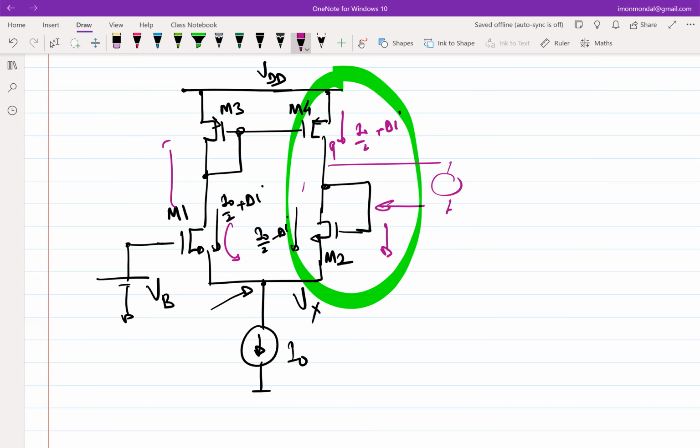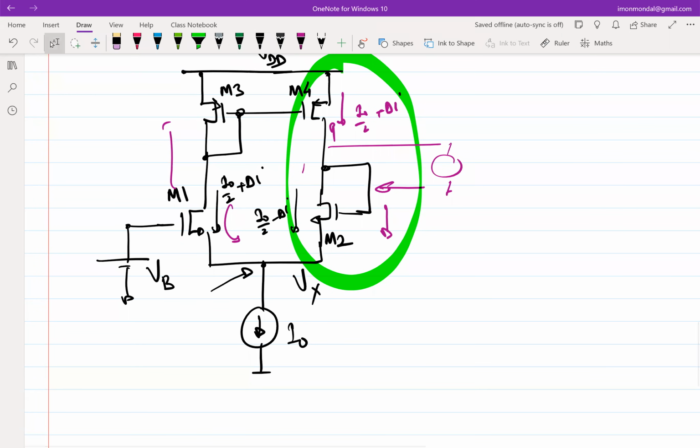So sir, whenever we are applying the test voltage here at the gate of M2, where gate and drain are shorted, that voltage is creating some current that is influencing M3, and M3 is influencing M4. Correct. And because of that, this should not be infinite resistance. Correct. See, another way of, okay. If you are not convinced with what I said, and you want a simpler way of looking at things, this should convince you.